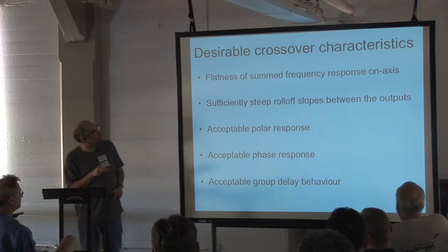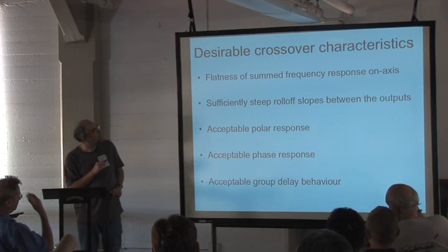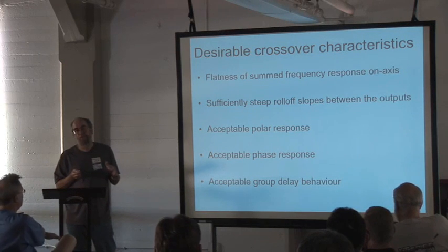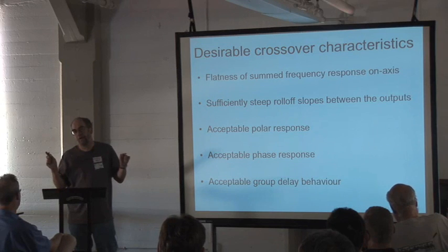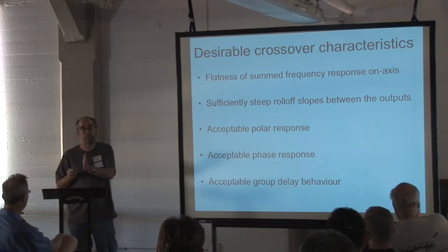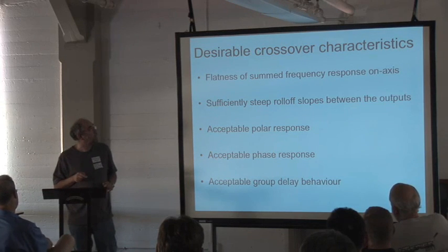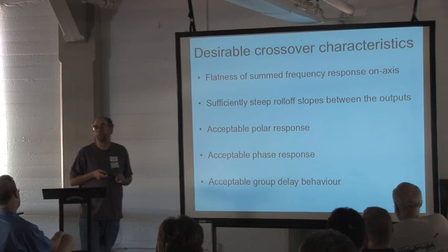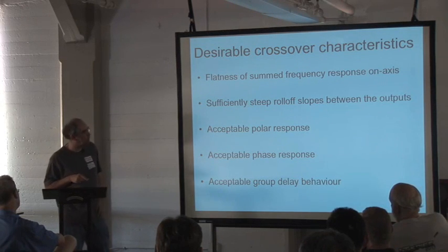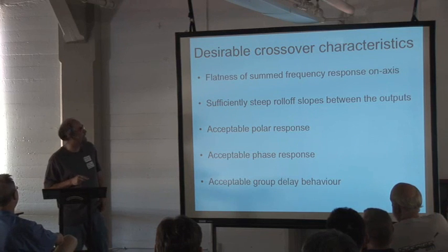Probably the next most important thing is to have a sufficiently steep roll-off on your filters, because you don't want frequencies going to the wrong drive unit, because they've probably got a bad response outside the area they're supposed to be used in. They've probably got high distortion compared with the middle of their range. And of course, you've always got the problem that if a lot of low frequency stuff gets into your high frequency unit, you're going to destroy it. It is going to explode, perhaps. I have actually seen a cone do that, shoot across the room when somebody got that wrong.